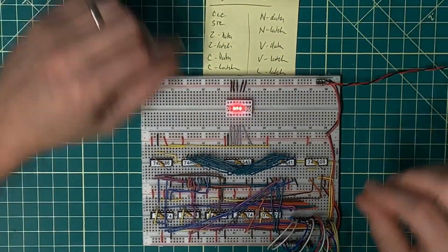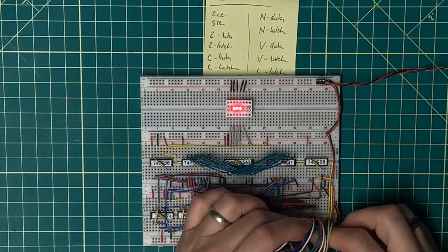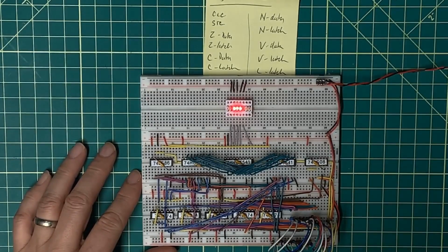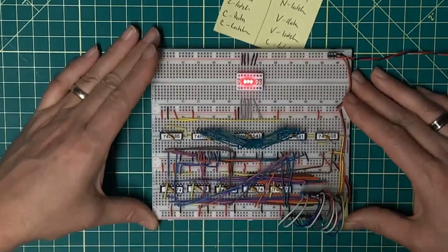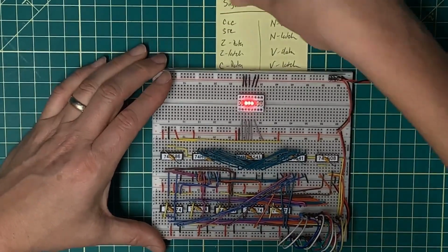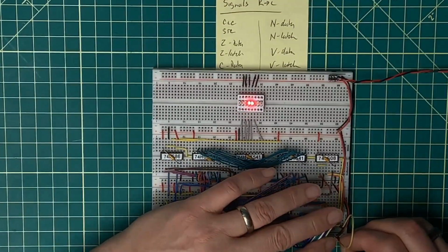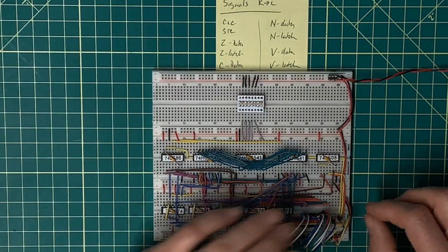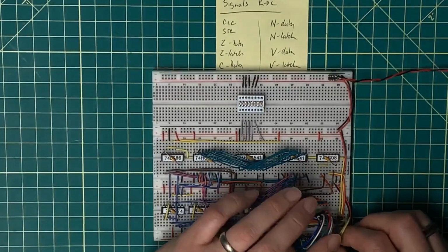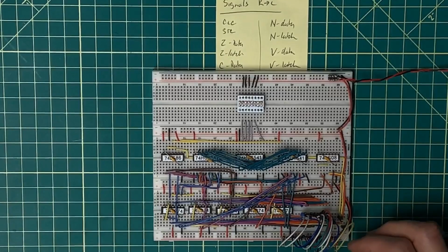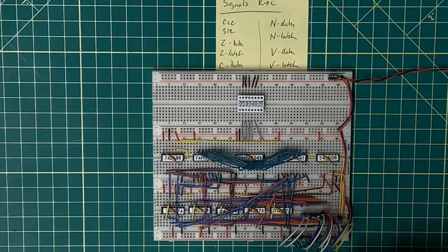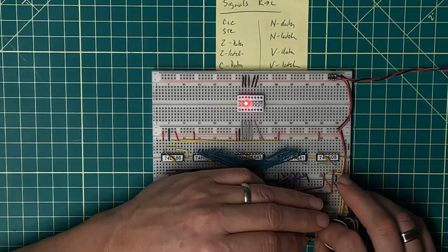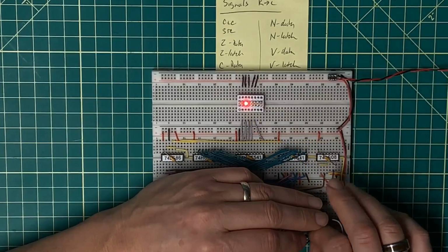Let's turn this on. I did hook up all of these wires here and brought them all up to a high state. I did some testing, it didn't work out well, and unfortunately I had the board down here like this, and so I didn't actually record it. But what I did discover is I had this down to a low state, this being the clear signal, and so no matter what I did, it was always clearing. And so when I changed that back to being at a high state or plugged into 5 volts, things started working better. So if this is set carry, I take that low and the carry indicator comes on,